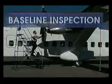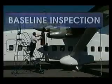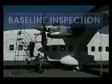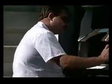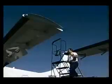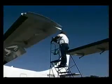To begin with, you must discover the extent of the existing corrosion problems of your fleet. To do this, you need to establish a baseline for each aircraft make and model you are operating. Theoretically, the oldest aircraft in your fleet will have the most severe corrosion problems, but this isn't always the case. Examine the service history of your aircraft and determine which aircraft of each make and model has been subjected to the most corrosive environment. Then select the aircraft which is the most likely candidate as the baseline.